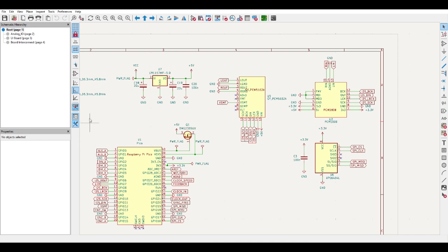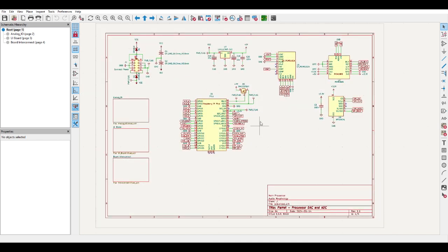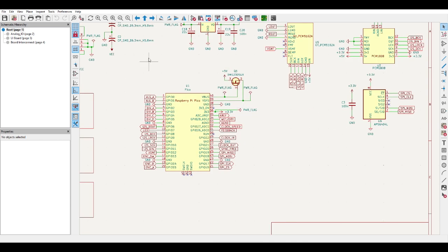So I had a quick count up of the connections between things that self-evidently need to be on the user interface board and things that could go on a second board, a backboard, and I reckon about 40 connections between one board and the other will be required.